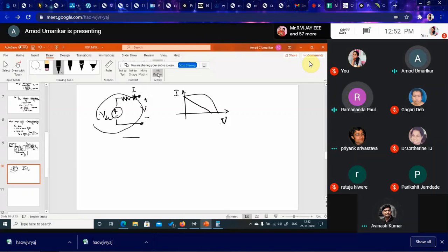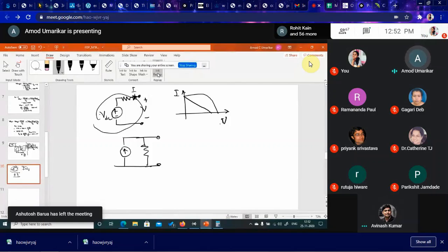So our motive is to get the maximum voltage. From the... we are not maximum. We have maximum voltage, which is VOC, minimum series resistance and maximum shunt resistance. So we have to maximize shunt resistance, which can be helpful to improve. When we see big solar PV systems, they are operating at MPP.